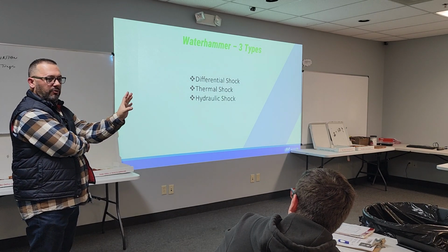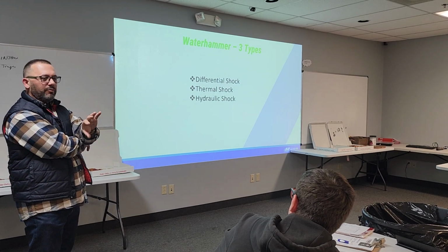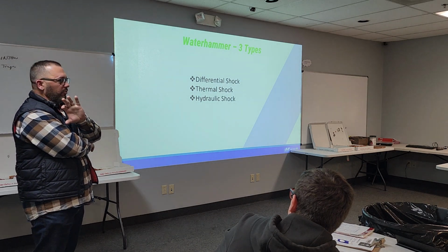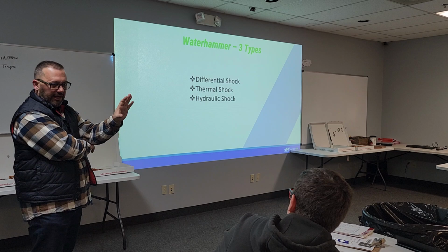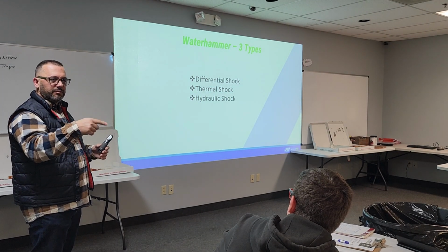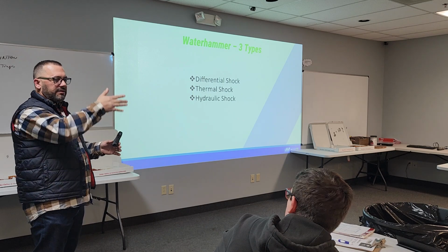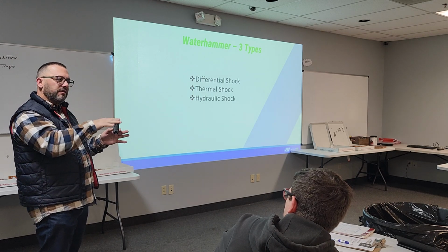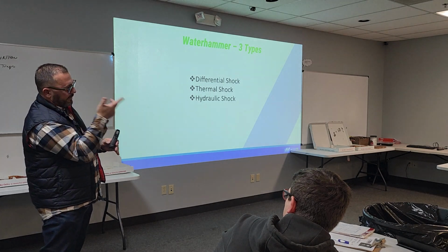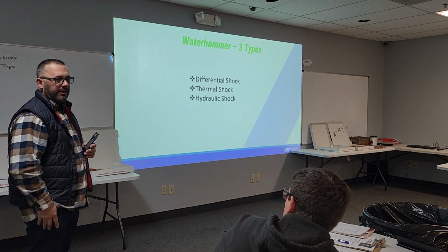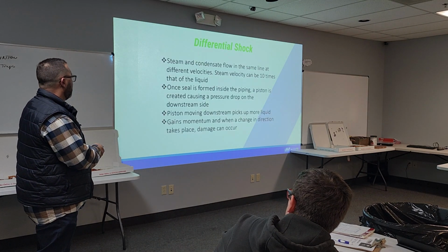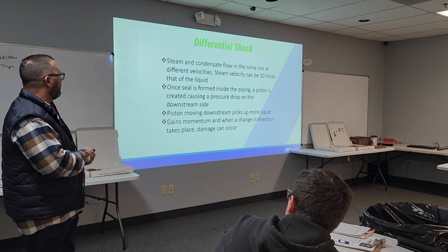And I'll have a water hammer display there, which will kind of be a mock-up. It won't be actual live steam and condensate return, but it'll be glass piping with green antifreeze and a black light over it with air hitting it. And what it's doing is basically creating wakes in the ID of that pipe. And once the full ID of that pipe gets filled with condensate, that's where it hits. And you guys have all heard it in plants, and damage can be done. And the truth is it's kind of fun mocking that little deal up.